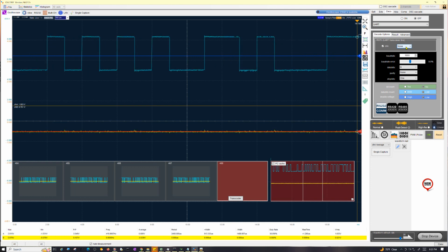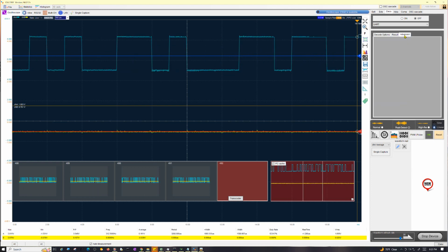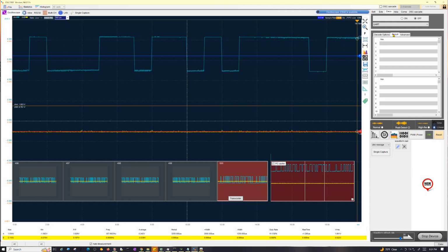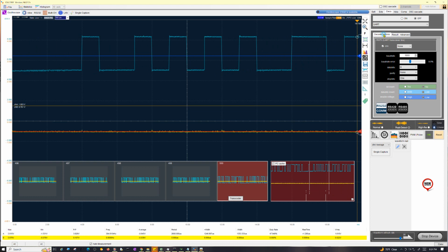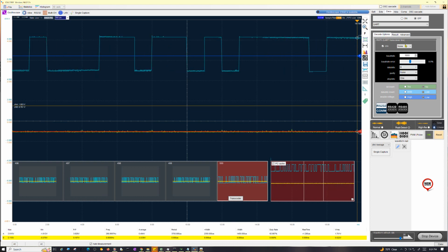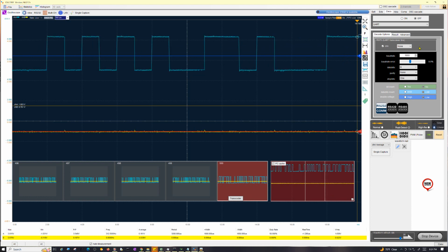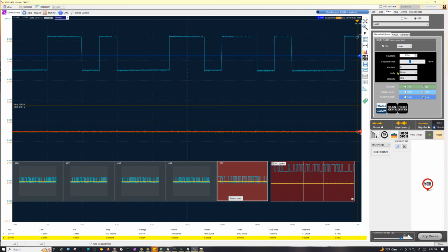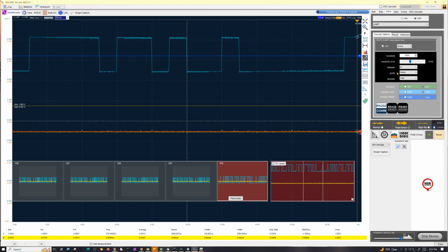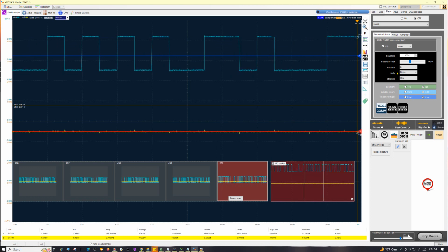That's a transmit. I don't know what you're supposed to do with it, because you can't actually transmit. As far as I can tell, this is just a listener. But you can hook it up to a transmit line and monitor the serial communications. You just can't actually act like a master of any kind in here like you can on the Analog Discovery, which if you want to pay $400, great. But on the other hand, that's got some quirks to it too.